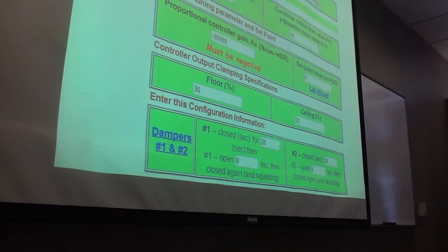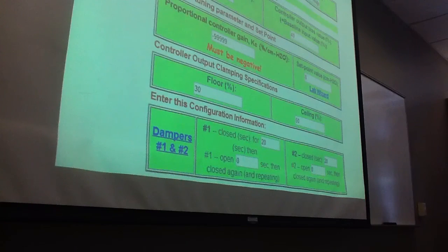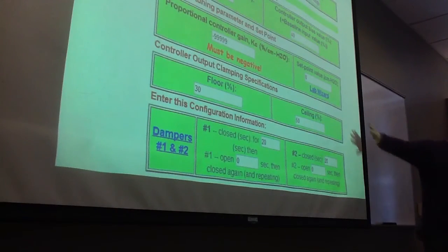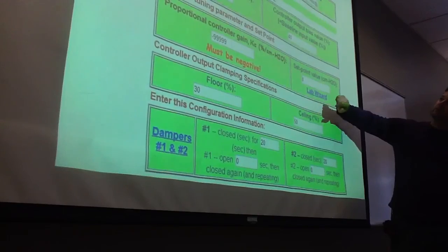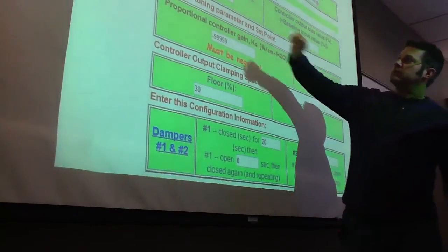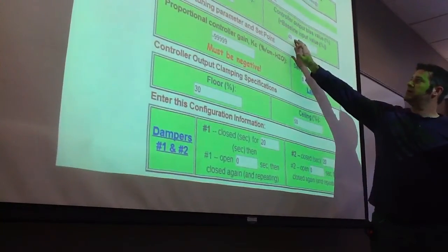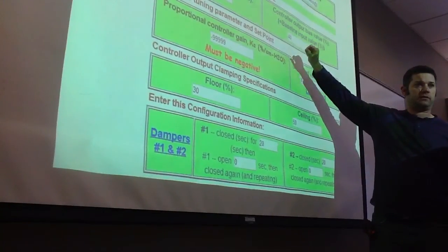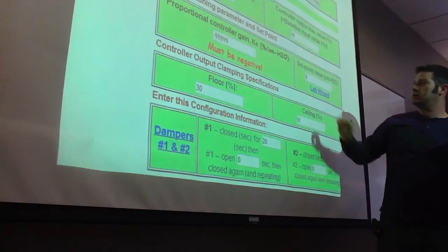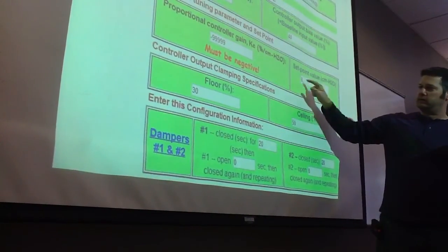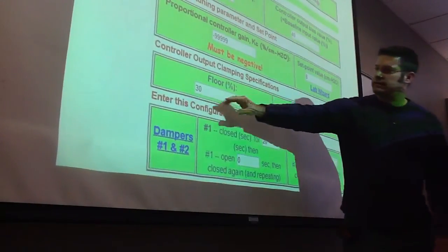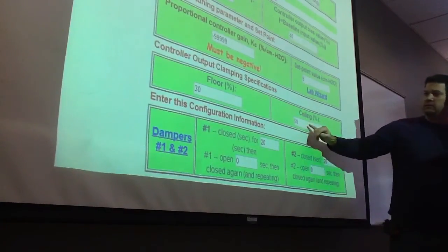And that was done using this slide, the control input. The length of the experiment was 20 seconds. The baseline was the 40 that we picked from our steady-state operating curve. The set point was 8, could have been 9. The floor was 30, the ceiling was 50.